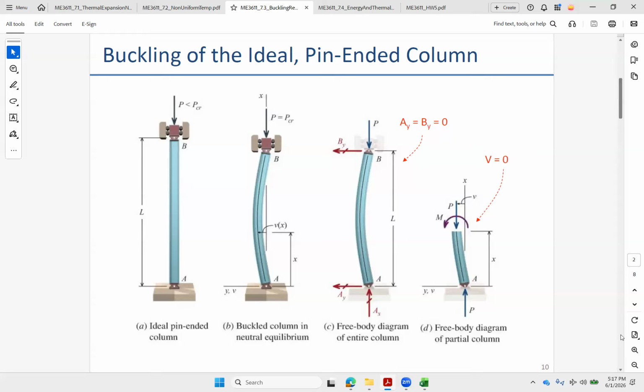And then I've got two compressive forces pushing all the way through the beam. Remember, that beam's still going to carry in the axial direction P all the way through, compressive. Only now this P is offset by however much it displaced out, that V right there. So right here, I can see I've got a balance of forces, P going up and down.